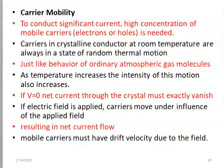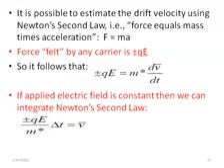But whenever you apply external voltage to this semiconductor, it will now align the free mobile charge carriers, electrons or holes, and they will start moving in the same direction. And this will create some amount of what? Current. And these mobile charge carriers, whenever they are moving in a given direction, definitely have what we call a drift velocity. Okay. It is also possible for us to estimate that drift velocity.